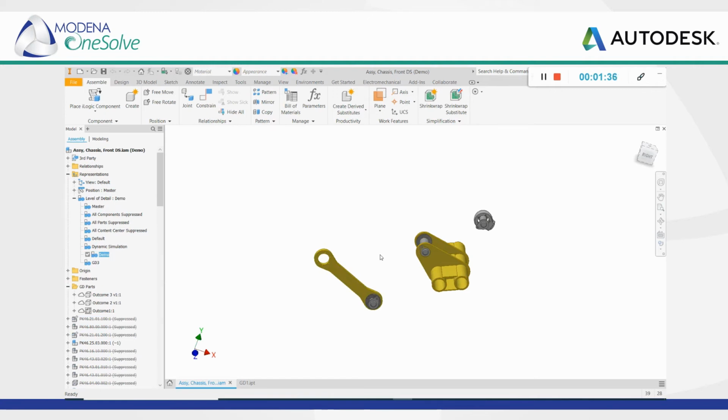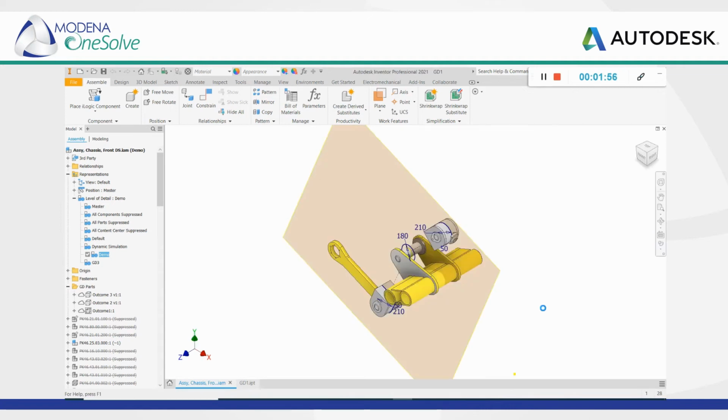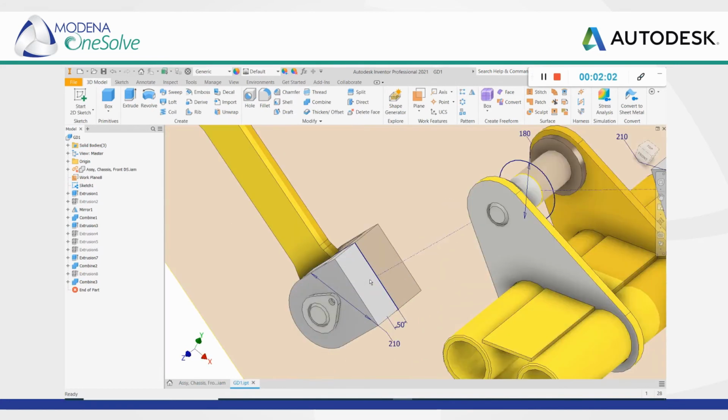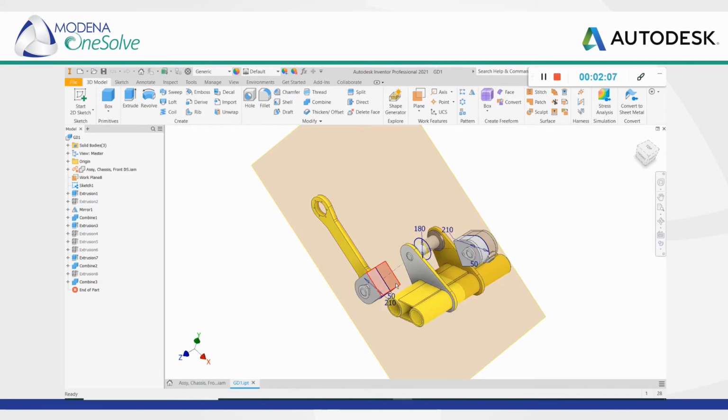What is that necessary geometry? It's going to be the obstacle geometry as to avoid collisions, as well as the key features, so the preserved geometry that generative design will use to build the part. From the step, once it's been isolated, we simply have to translate this information into a new part file. This is done by using derived. Once we derived it, it's taken into the new part file and we can start making any additional changes or features that we may require to perform the generative design process.